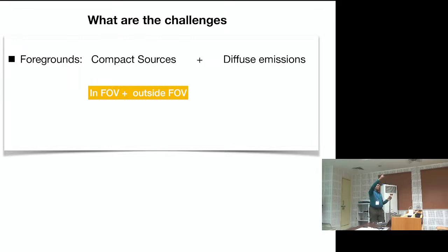If you remember, yesterday we were looking at the antenna in the other room, the Yagi antenna. It had a reflector on one side, and then you have the other elements. Once you rotate it, you get the maximum response when the entire Yagi is parallel to the dipole that is receiving it. As you rotate it, the response reduces, but it never goes to zero. That it never goes to zero is not because there is some electronic error in there. It is also because the antenna radiates something in those directions.